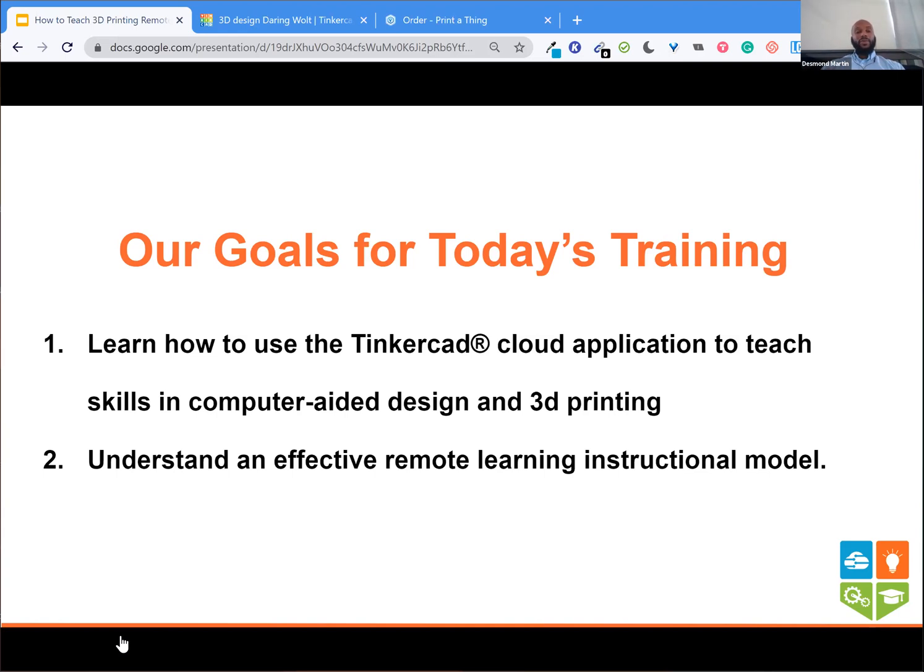When we think about 3D printing, the first thing we actually need is something to print. I like to break down 3D printing as a three-step process whenever I explain it to educators. You have the design, where you are actually generating a three-dimensional object digitally. The second part of that is the slicing. Slicing is where we take the raw numbers of our three-dimensional object or objects and translate that into code, into specific instructions that our actual 3D printer will follow to produce our object.